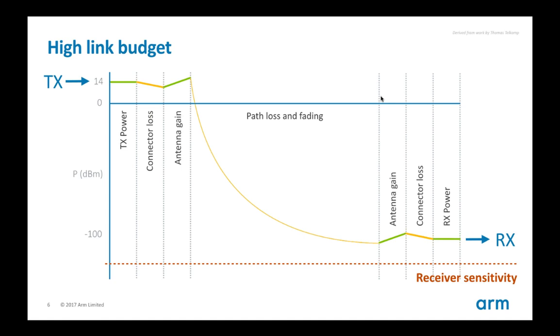This is where a bit of the magic of LoRa is. LoRa's modulation scheme is really good, and because of how LoRa modulation works, through chirp spread spectrum, LoRa is actually able to detect signals under the noise floor. So where you normally wouldn't get any signal anymore, LoRa can still decode that. That's why the receiver sensitivity of LoRa is very good. Typical LoRa receiver sensitivity is minus 137 dBm.